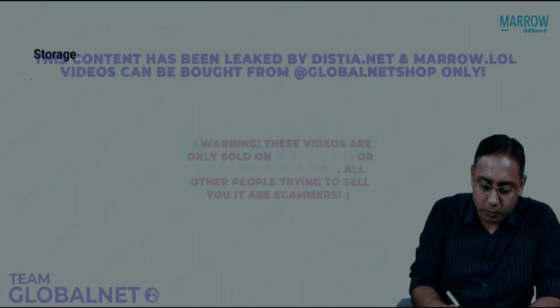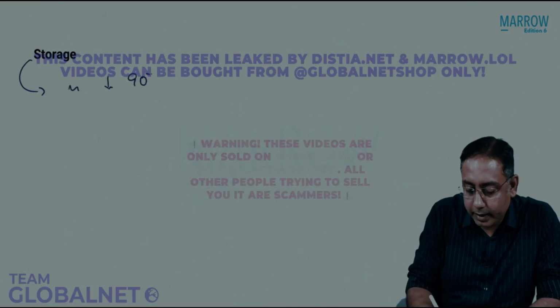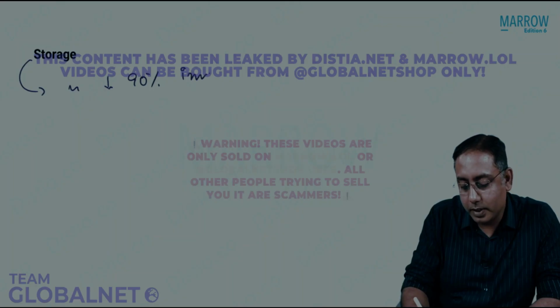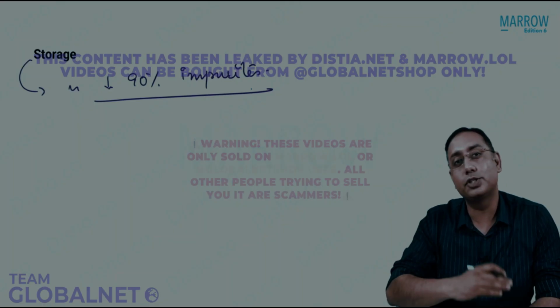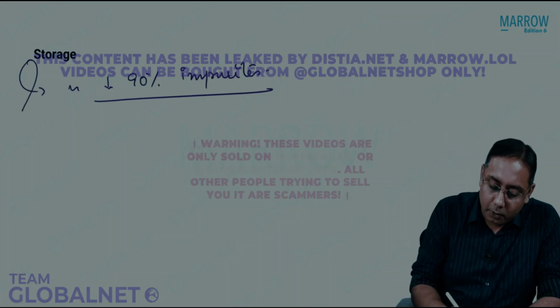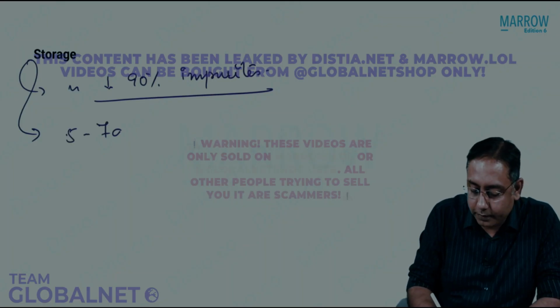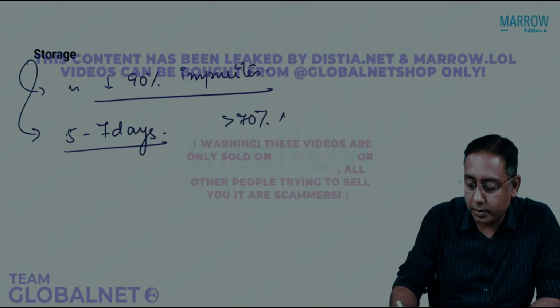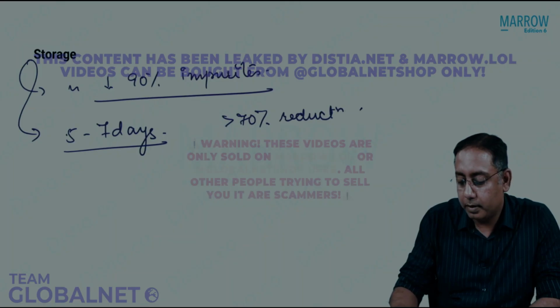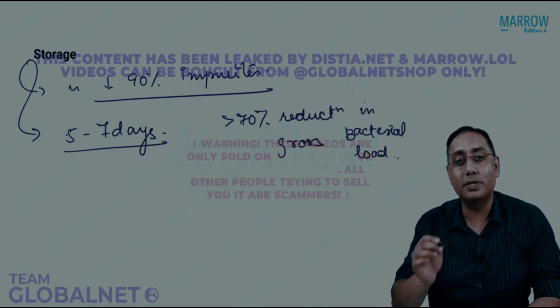If you talk about storage of water, by storing water, it is believed that more than 90% of the impurities will settle. Impurities will decrease by more than 90% by storage of water only. How much time should we store the water? It is said that if we store the water for 5 to 7 days, there is more than 70% reduction in gross bacterial load.